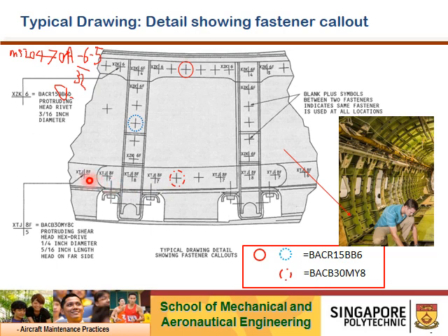All right. So of course, if you look carefully, you have this 8F. So it's 8. Just take note. We will talk about this when we cover the fasteners. But over here, this is a bolt. It's a protruding shear head hex drive bolt. A bolt is slightly different from rivets when it comes to the diameter. In this case, for a bolt, the diameter denominator is 16, which is mentioned here. 8 over 16 is 1/4. This one we will cover during the other unit, fasteners.